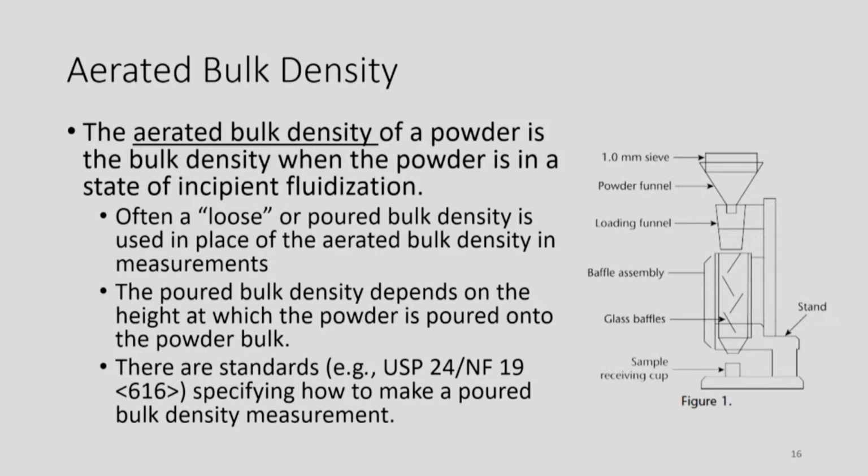Again, it's common. How many of you measured bulk density in lab? Most of you, right? So you make it flow through a funnel, right? And then it falls into a container, and then you get the weight, right? So that's common. For grains and larger materials, you will not use this kind of baffle assembly, but it's most commonly used for small fine powders. Okay.